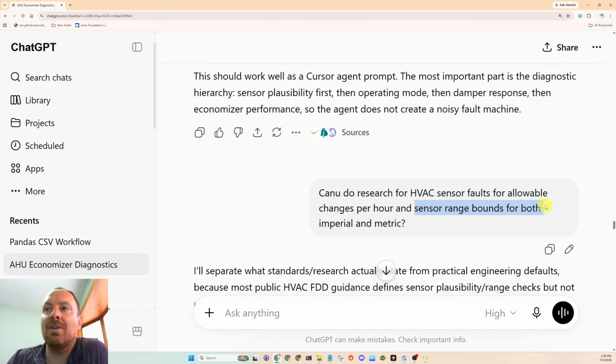Sometimes in building automation, the technicians set it so if the zone in an occupied building falls below 68 degrees Fahrenheit or above 80, that's a building automation alarm. So that's comfort ranges, but in fault detection algorithms, we can do more of a range where this is a bad sensor. It shouldn't be reading anything like that.